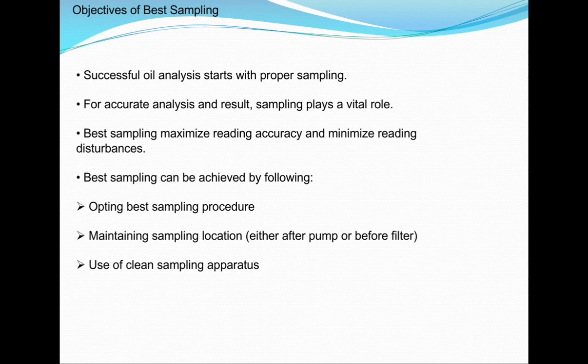So here we see the best sampling practices. We'll see what practices we have to follow for best sampling. The first point is that a separate sampling point must be provided to take samples. Means in a pump, you see there is a level system, then we have to see where to take the sample.